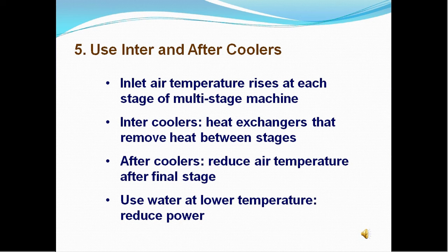After coolers. As mechanical energy is applied to a gas for compression, the temperature of the gas increases. After coolers are installed after the final stage of compression to reduce the air temperature. As the air temperature is reduced, water vapor in the air is condensed, separated, collected, and drained from the system. Use of water at lower temperature reduces specific power consumption. However, very low cooling water temperature could result in condensation of moisture in the air, which if not removed would lead to cylinder damage.